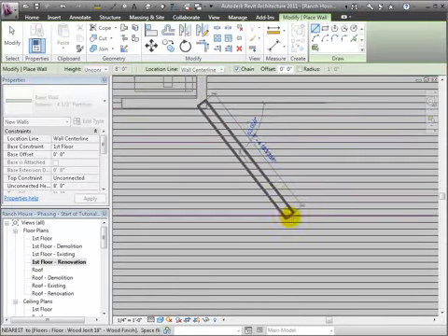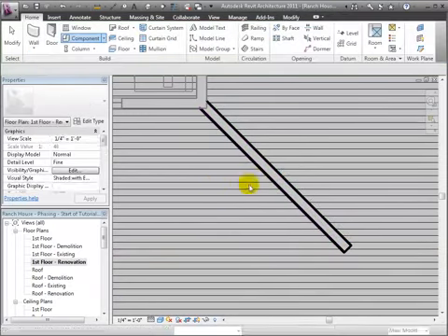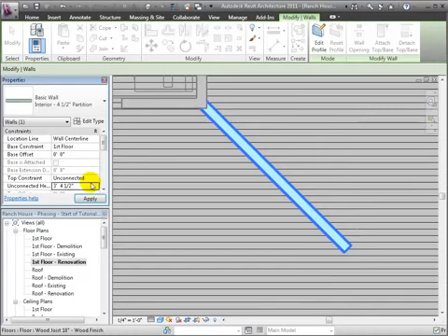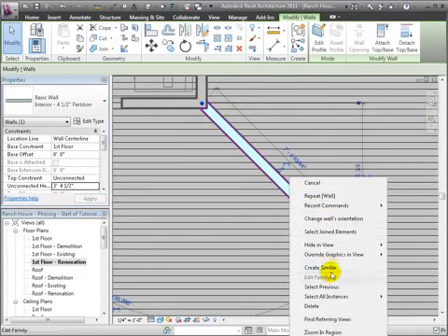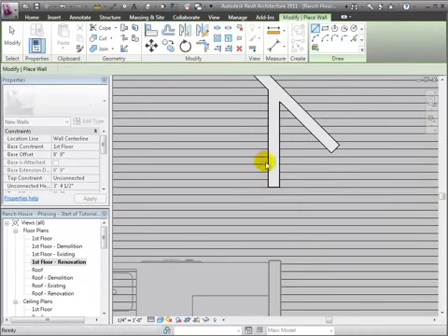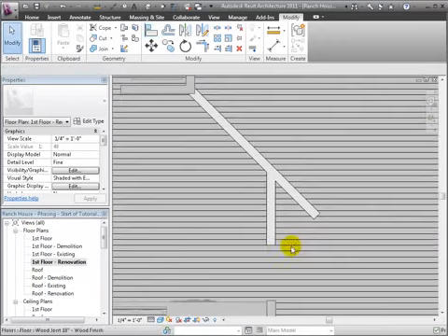We'll create this wall out at a 45-degree angle. I can make it an arbitrary length because later I will trim it. And then another wall segment going straight down, not at a 45-degree angle, but rather parallel to this wall down here. I can draw it first to be around 3 feet, and then I can trim it. Align it so that it aligns with this nearby kitchen wall to have a clean line.